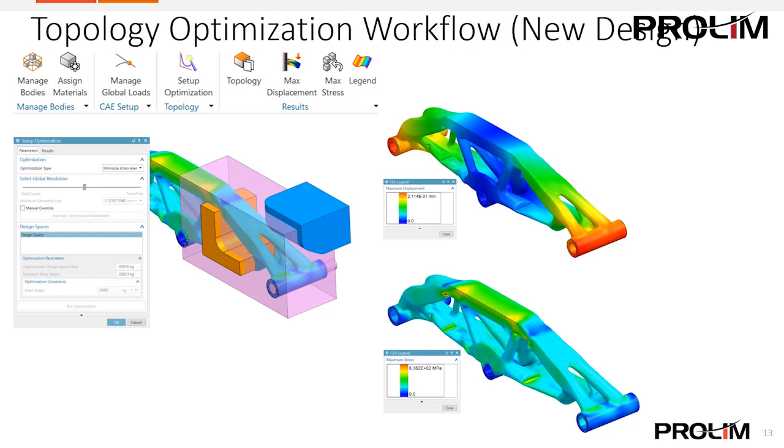Once we had all of our bodies managed and all of our constraints added that we wanted, we went up to set up optimization. From here, we put in our mass target that we wanted to shoot for, selected the optimization type, and ran the optimization. From there, we looked at the three bodies that it created. We looked at the max displacement and the legend there, and then we looked at our max stress.